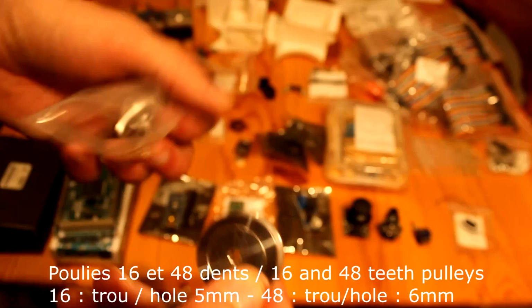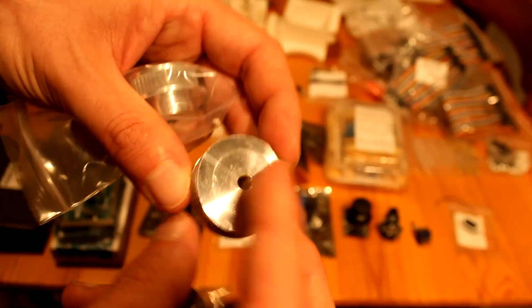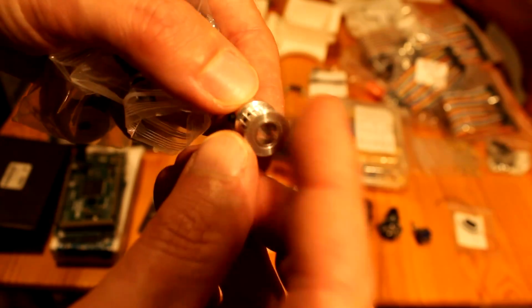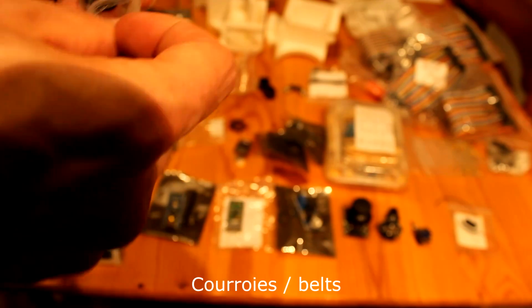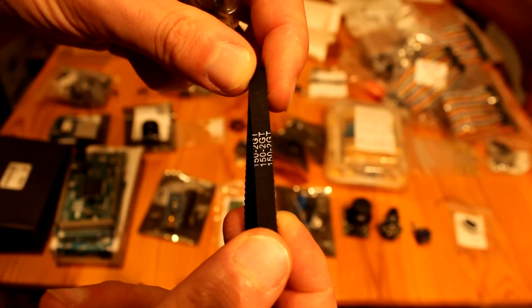The pulleys. These are 48 teeth pulleys and 16 teeth pulleys with a reduction factor of 3 for better precision. Beware of the hole diameters. I made a mistake initially, because the hole needed for my EQ5 was 6 millimeters and the hole was 5 millimeters, so I had to drill it to enlarge the hole. These are GT2 pulleys with 6 millimeters thickness, and the belts are GT2 6 millimeters belts in 150 length, but the 148 centimeters length was the better size for my EQ5.